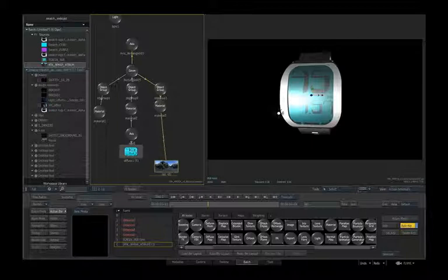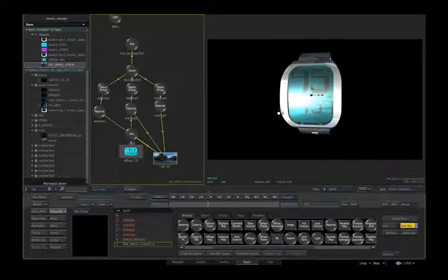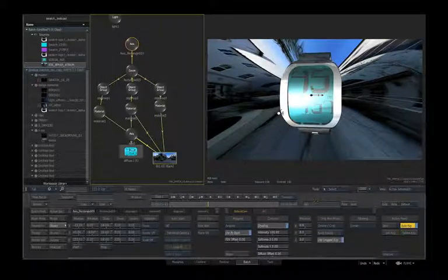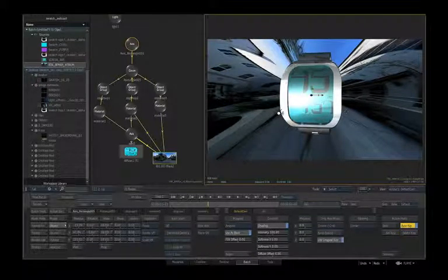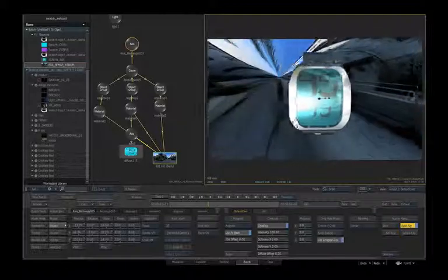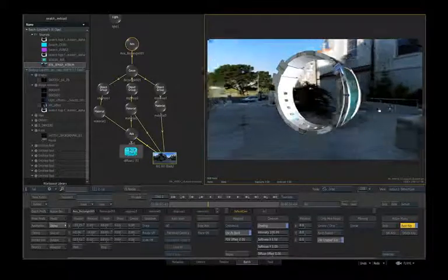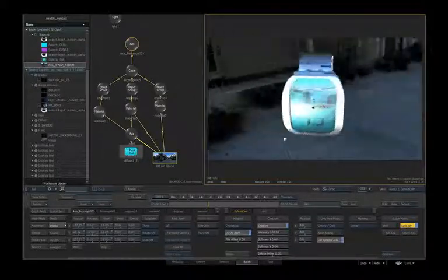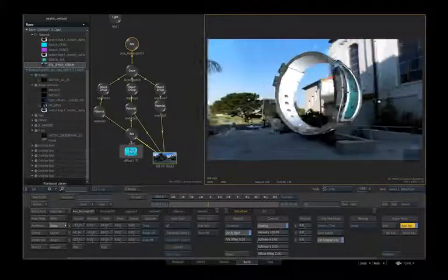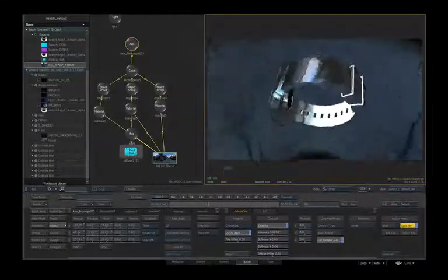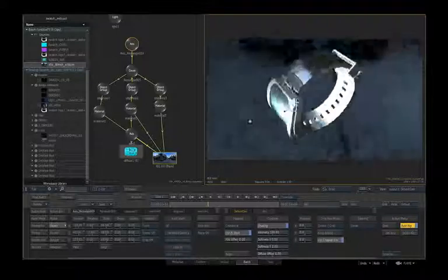And what you'll see is, if I use these guys for example, and this, all three of them, exactly what an IBL does is it literally creates environmental lighting. We can look at it as a background if we'd like. So this is now a sort of background environment. It's not mapped correctly yet. Let's go ahead and cylindrical map this, and you'll start to see how this process works, where I'm using this environment as a way of casting reflection or indirect lighting onto this watch model here.